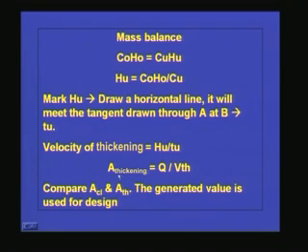So, we got two areas, one for thickening and one for clarification. So, two areas are there. Compare these two areas, and if you want to meet both the purposes, we have to provide the area which is maximum. Then only we will be able to meet both the criteria.